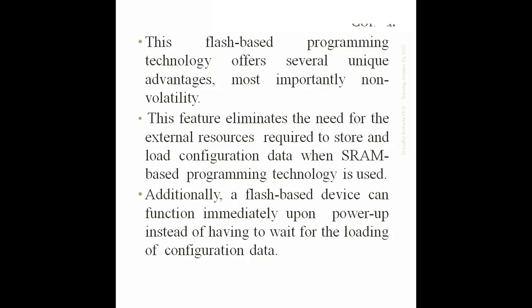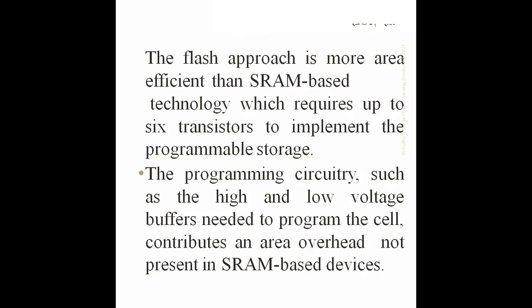And this flash-based program technology offers several unique advantages. Most important, non-volatility. The feature eliminates the need for external resources required to store and load configuration data when SRAM-based technology is used. The flash-based device can function immediately upon power on, instead of waiting for the loading of configuration data. A flash approach is also more area efficient than SRAM-based technology, which requires up to 6 transistors to implement the program storage as in the SRAM.